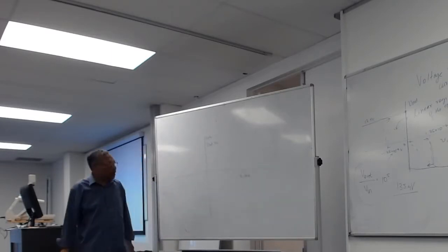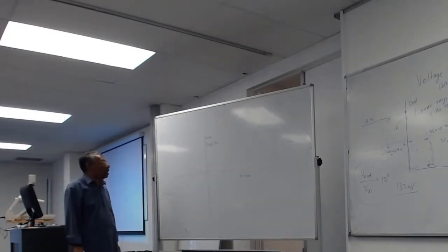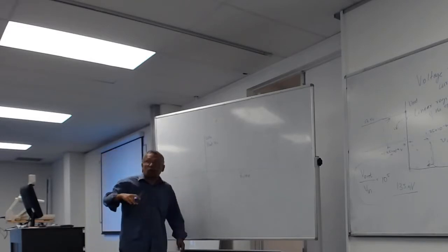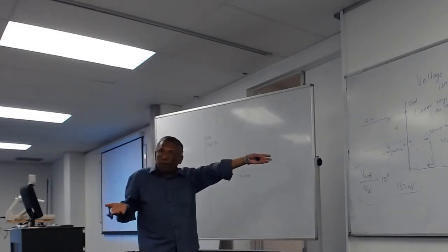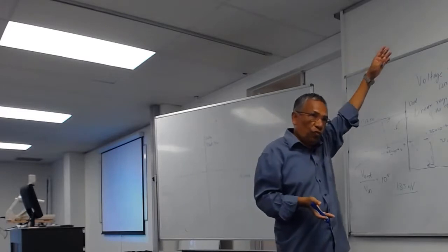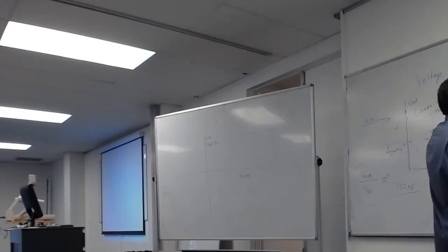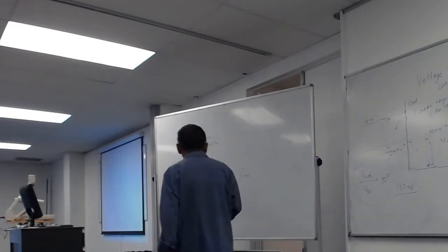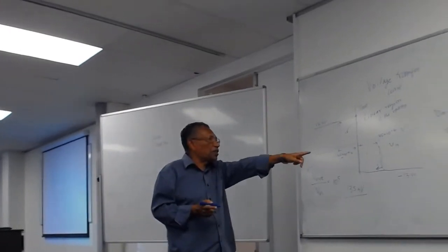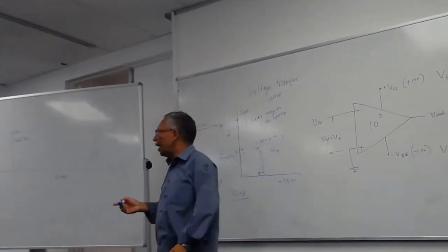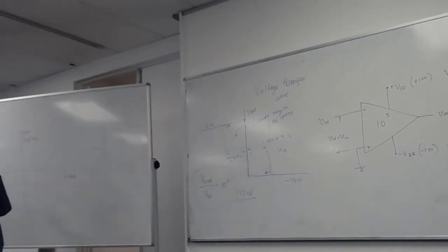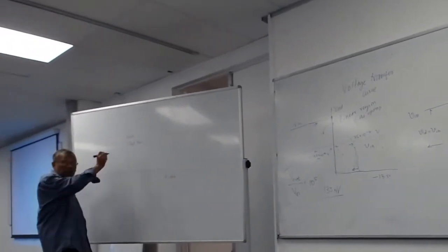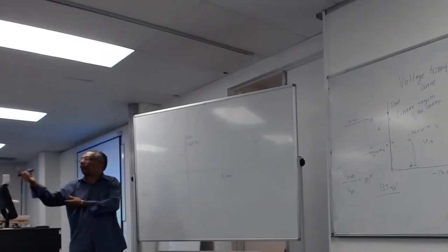So you have a time axis and your voltage axis. The output voltage, because it is like a comparator, will swing to full voltage this way or full voltage this way, so it depends on the input voltage. If you look at this circuit and plot here, say I have got an input voltage, I will draw the input voltage, then you draw the output voltage for me for that circuit.